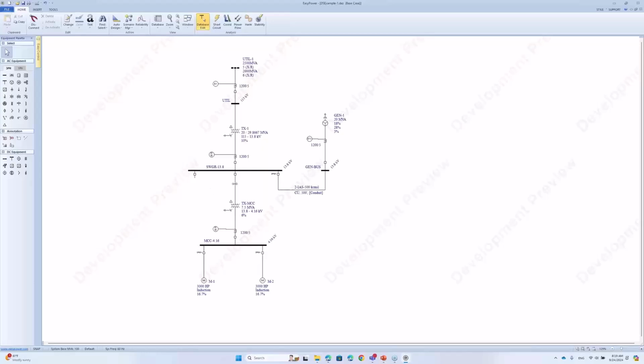Then the next example we're going to show is that after I include the motor and incorporate the generator dynamic stability model and recalculate the arc flash, we will see the difference introduced by the dynamic stability model of the generator and motor contribution to the bus fault and the arc flash. Make sense? So let's make sure EasyPower is doing the right thing, and then say what other things dynamic stability EasyPower can do that the short circuit focus cannot do.